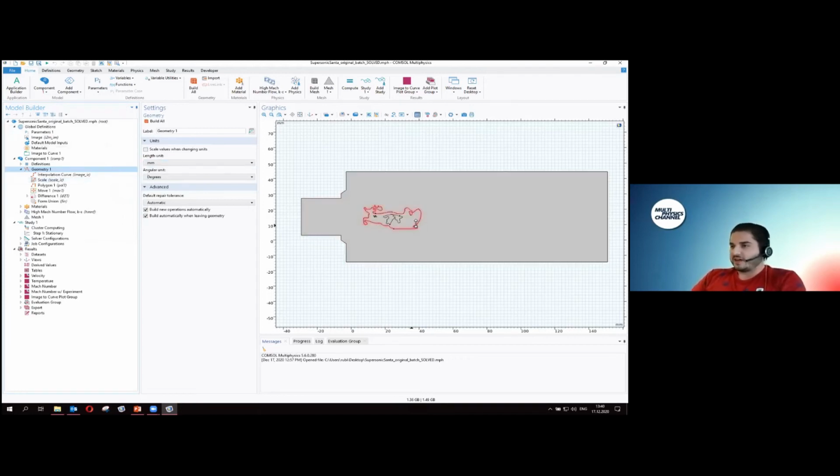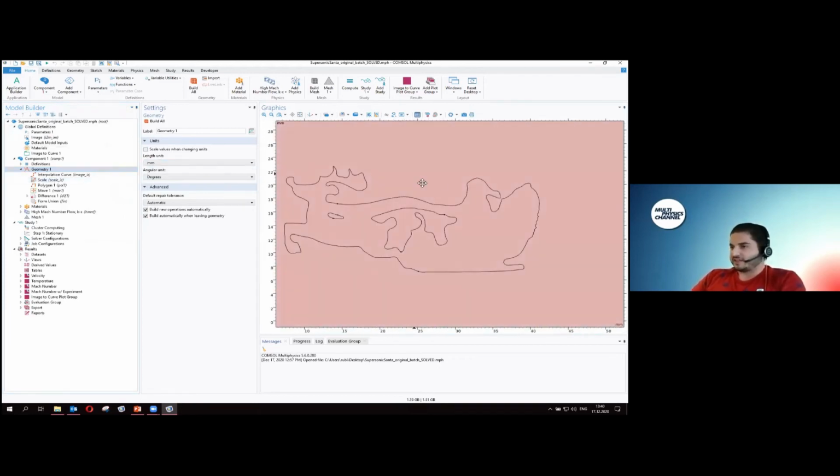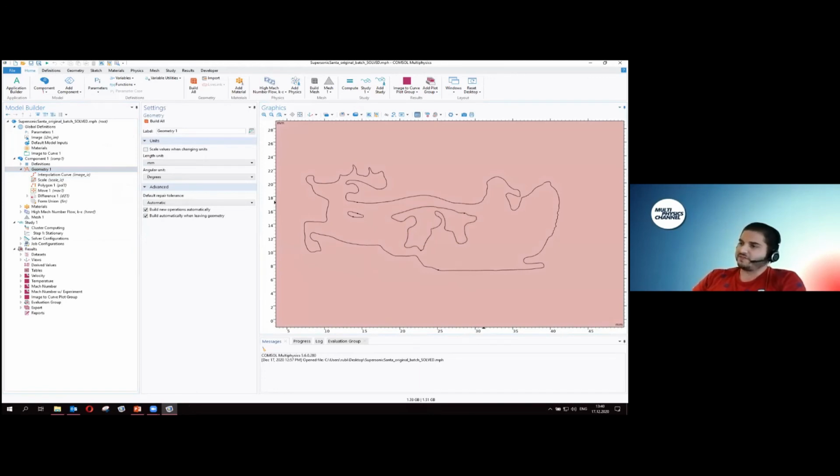Good. Once you have imported the curve, and that is, as I said, automatic, I chose here to have this converted as a solid. That means afterwards I can easily perform an operation like taking away this shape from another solid domain, and it remains just blank. And those are the walls we afterwards want.